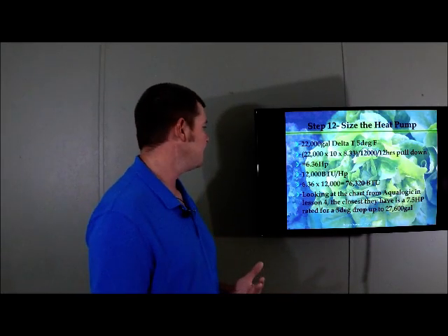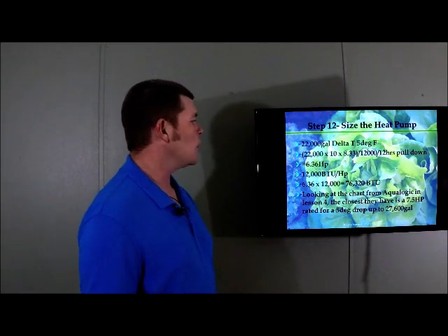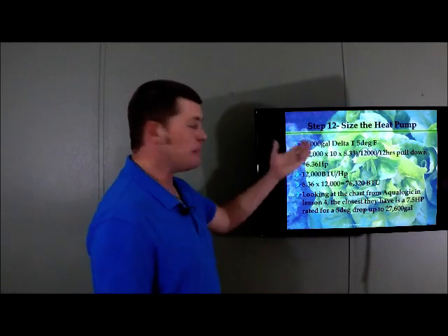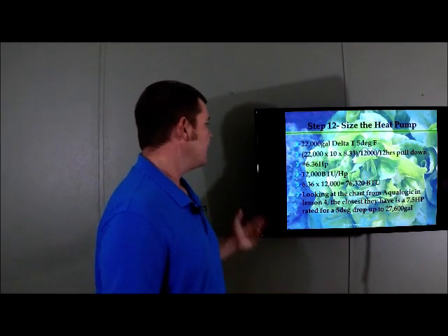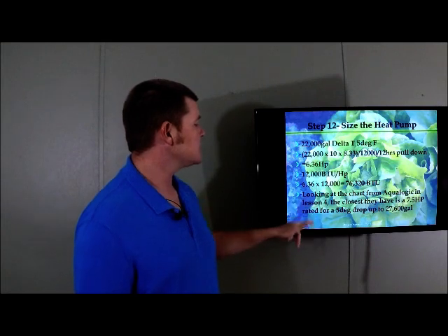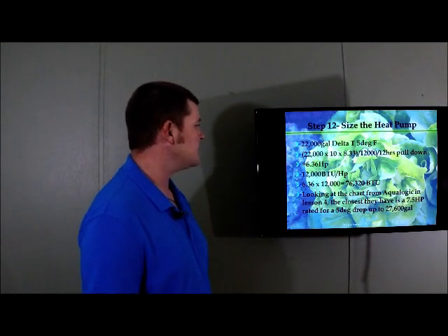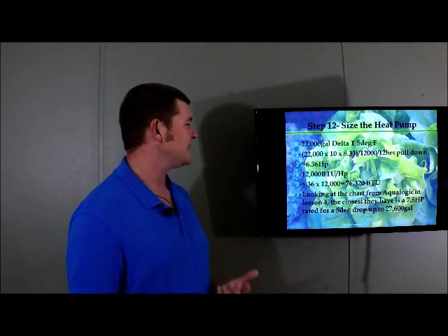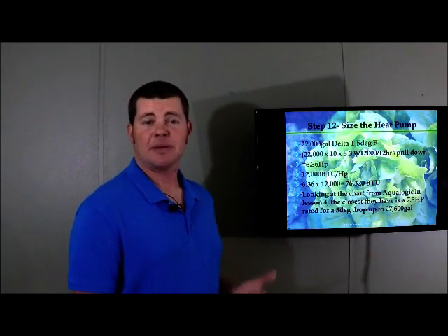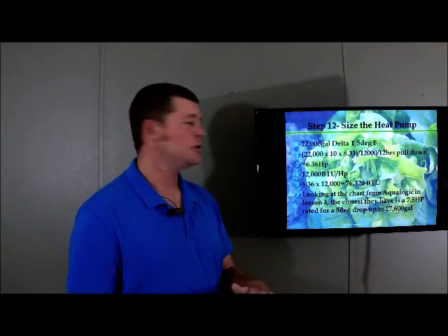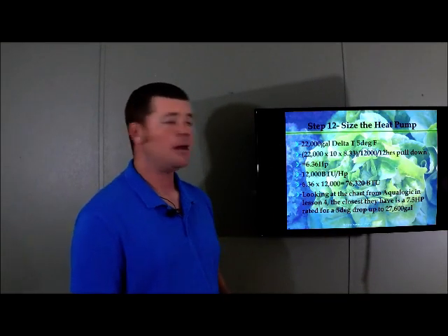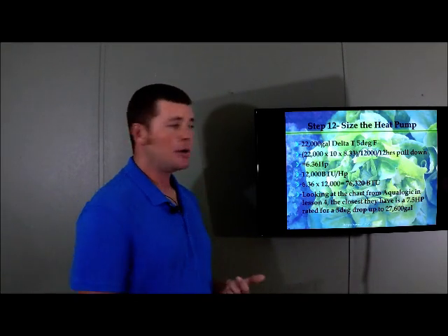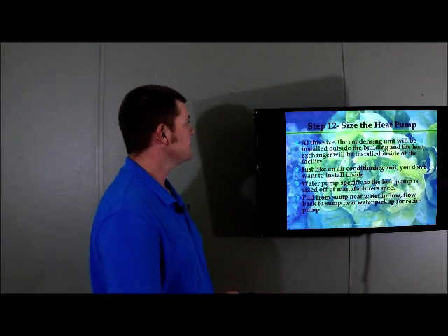76,320 BTU. Now, if I look at a chart from Aqualogic, who is a large supplier of recirculating aquaculture heat pumps, okay, they supply this equipment. If we look at one of their charts, which I have in lesson 4, the closest they have is a 7.5 horsepower that's rated for a 5 degree drop up to 27,600 gallons. So because that's the closest, the next smaller unit I think is a 5 horsepower and it won't do the job. This one will. That's the right unit. We picked that. We just sized the heat pump for the recirculating aquaculture system.